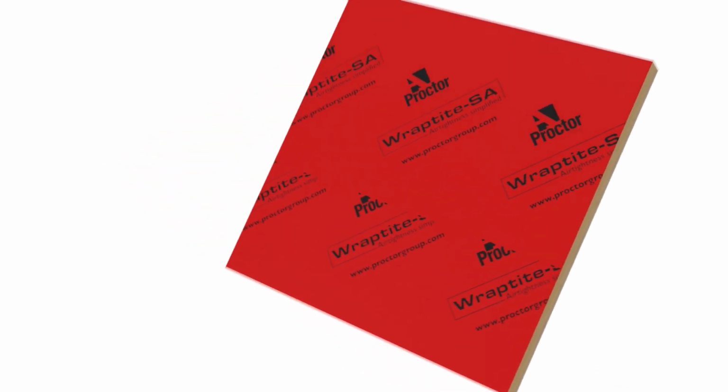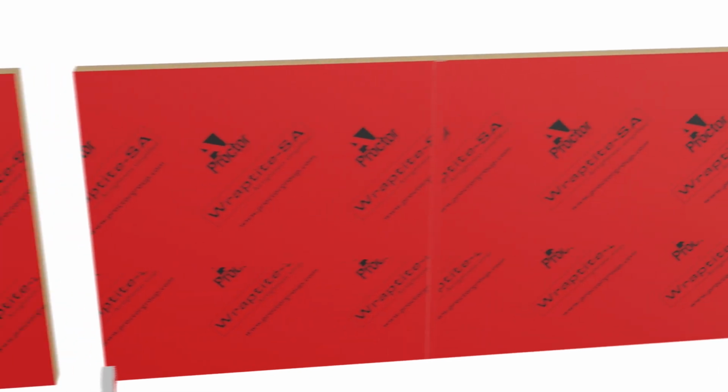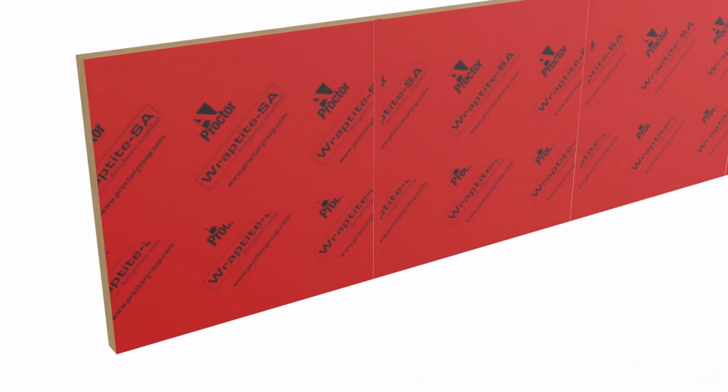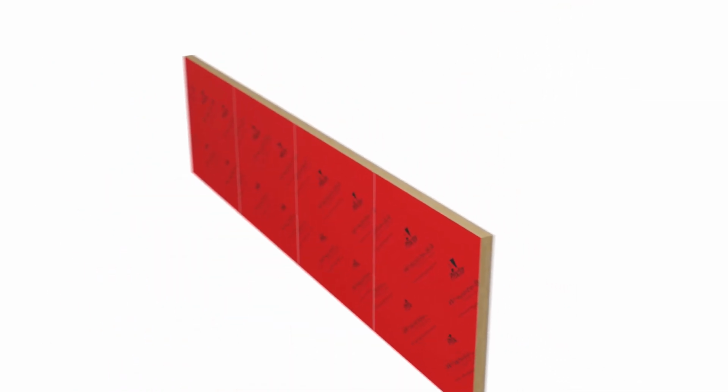The panels are then assembled and the joints taped using the same material in tape form, ensuring no adhesion issues or tape compatibility problems. Once the joints are taped, the panel assembly is resistant to air leakage, and any service installations such as wiring or pipework can be undertaken independently without risking damage to the airtight layer.